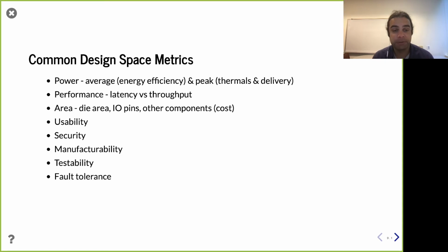The really insightful question from Chao was asking, wait a second, here we are working at the Chisel and FIRRTL level, and at that level, how am I supposed to get these metrics like performance or area? That's kind of detached. Yes, that's absolutely correct. At the level of Chisel, all you know is how many cycles something will take. When you run in simulation in Treadle or Verilator, you can see for my design on this testbench stimulus how many cycles it takes to solve this problem. So all you know is cycle count, which is one measure of performance, but in terms of turning it into an absolute real world time, you need to know the clock frequency. In order to know the clock frequency, you need to know what's going on. So the answer, of course, is yes.